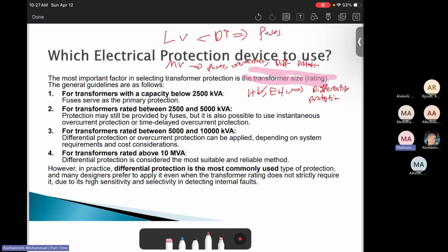Then the branch falls down to the ground, and once it falls, the main reason for the fault disappears. Therefore, this fault is temporary. It is not lasting forever. So why would we need to disconnect the power for a long period and send maintenance to reconnect it? There is no need for that.